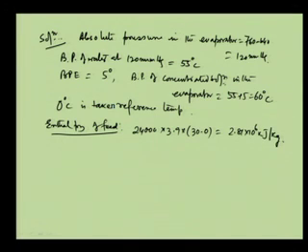Similarly, the enthalpy of vapor generated. To find out the vapor generated, what do we have to do? We have to do the mass balance. So, if I take the basis as 1 hour, the feed equals 24,000 kg.